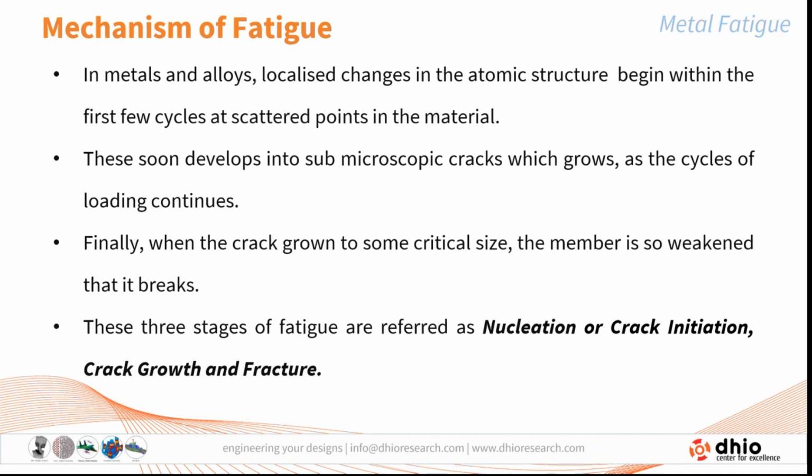Then these soon develop into submicroscopic cracks, which grow as the cyclic loading continues. And finally, when the crack grows to some critical size, at which the remaining material cross-section area cannot resist the given loading condition, the member breaks.